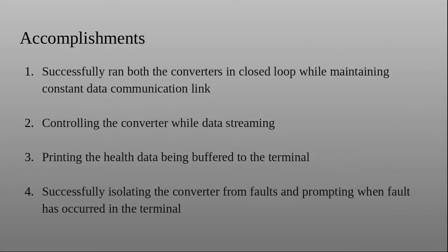Coming to the accomplishments we have achieved, we have successfully been able to run both the converters in closed loop while maintaining a constant data communication link with a Linux terminal. We were able to control the converter while data streaming. We were also able to print the health data being buffered to the terminal, and this health data would mostly comprise the status bits for the converter, and this status bit is custom designed for the converter.